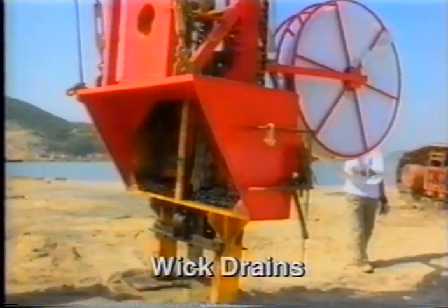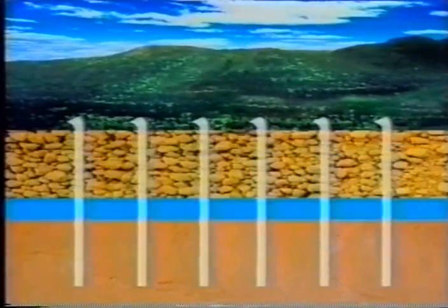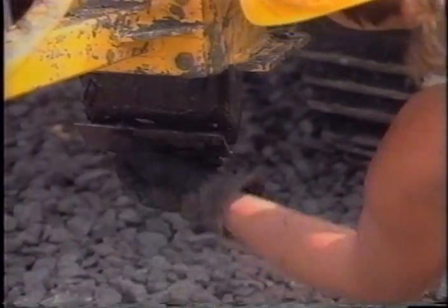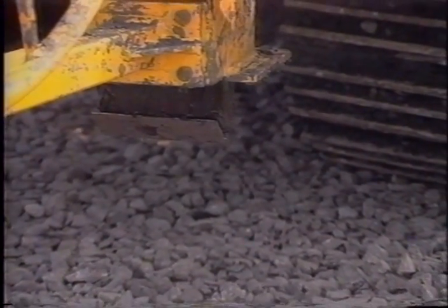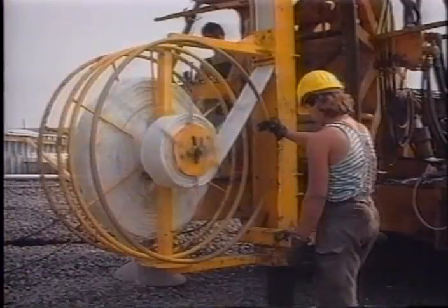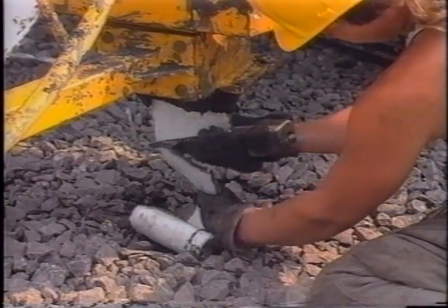Composite wick drains are inserted vertically into the foundation soils to consolidate saturated soils like clays and silts. The pore water, under pressure exerted by the surcharge load, is forced upwards through the drains. A metal plate or shoe is attached to the drainage wick protruding from the bottom end of the piercing device. The wick is installed to the required depth via the lance and left in position below ground. The lance is then extracted and the end of the drainage wick cut off.